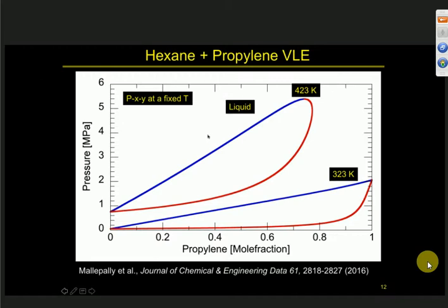So here, you start out at a liquid single phase, then you drop the pressure, and you hit the first bubble, that is the bubble point. Then you keep on going, more and more into the liquid plus vapor region. Then as you drop the pressure, you hit the saturated vapor curve. As you keep on going, you go into the completely vapor phase.